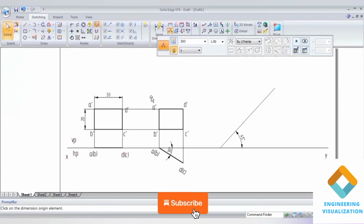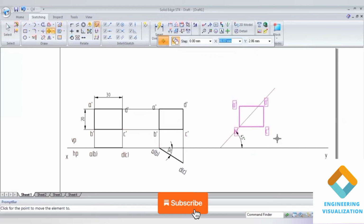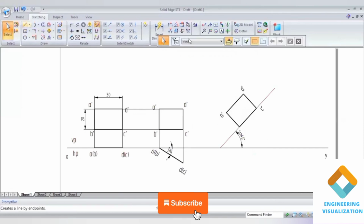I'll select this second position front view, create a copy of it and select the vertical edge here. I'll select this B dash, go to rotate, select this B dash to C dash and place it on the angle line. Then project downward to complete the final position.